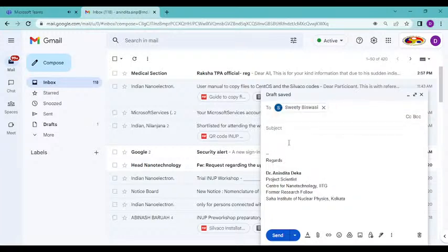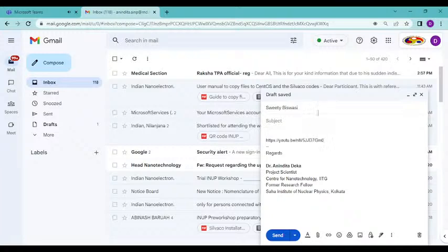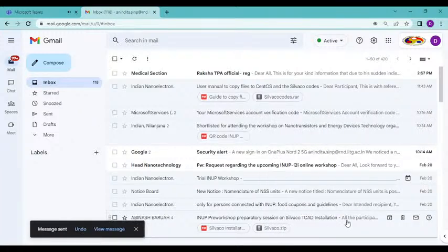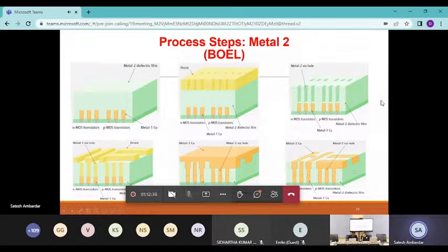the transistors are in the active area, and each of these transistors are interconnected through vias to the different metal lines, and we have a stack of metal lines before it is sent for the final processing. Then the wafers are tested, and the good dies are binned out and sent for packaging. So I have just given you an overall high level definition of how the process steps are involved. As I mentioned, there are about 700 to 800 process steps in the fab, essentially involving these steps only: deposition of the metal layers, creating channels, creating drains, implantation process, CMP process, creating vias, and then the dielectrics and the metal lines.